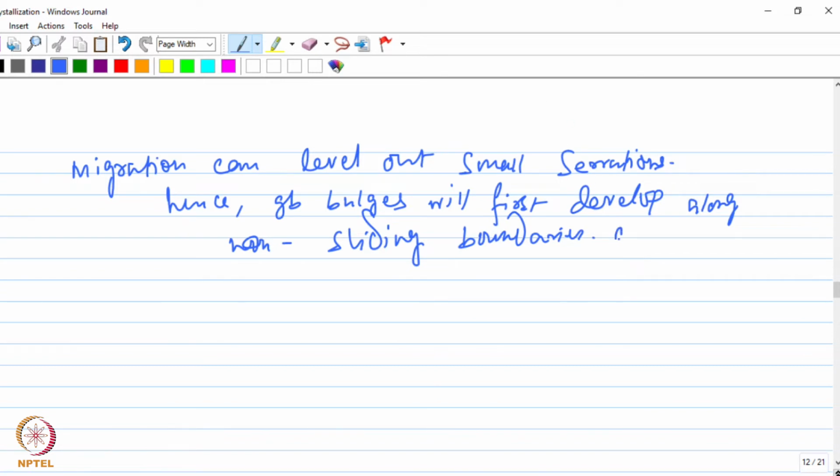And this would occur at large strain, while the dislocations arrange and form the low angle boundaries at lower strain. Okay. So once the bulges form, sliding can still occur in small areas of the grain boundary, and the rest of the boundary has to accommodate the strain by plastic deformation, leading to formation of a mantle kind of shape.